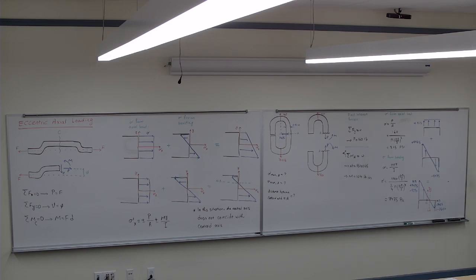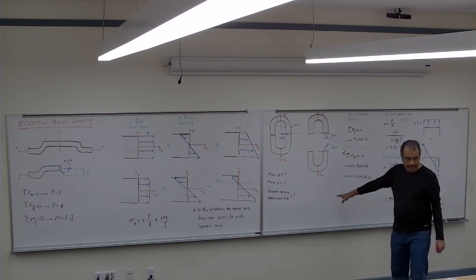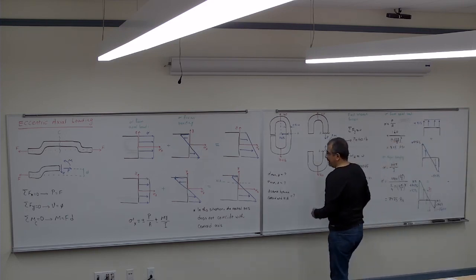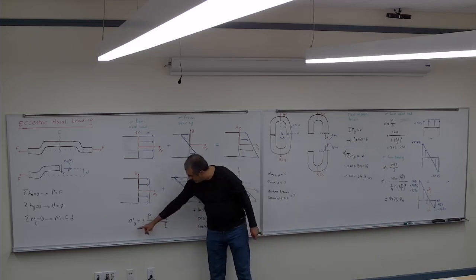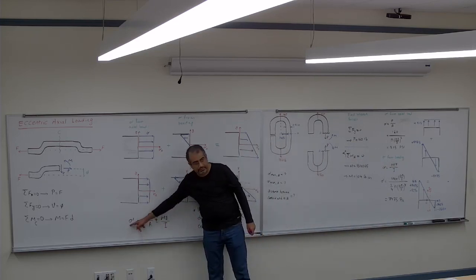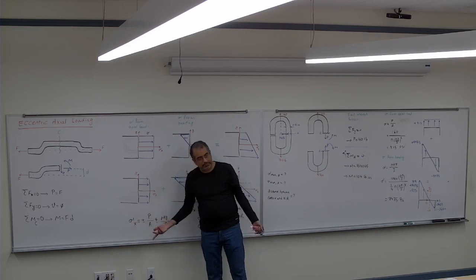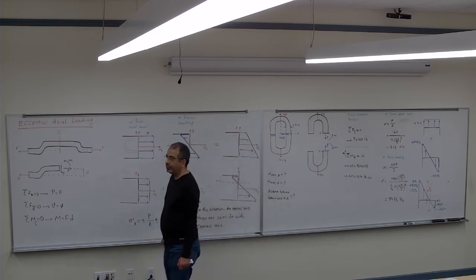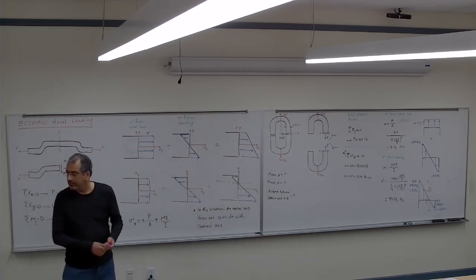One way is to use the geometry of that shape, the two triangles, and try to find either of these two distances. But we have that distance, we have this distance, you have to try to find that distance either from here or there. So if you find that distance and you know that's going to be the center, you can do it. The other way that we can do it, the way the book writes it, is: what's happening on the neutral axis? Sigma would be 0, correct? So on the neutral axis, the sigma would be 0.